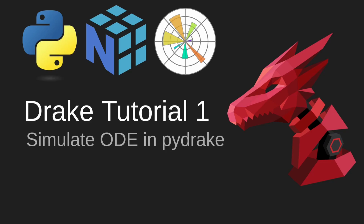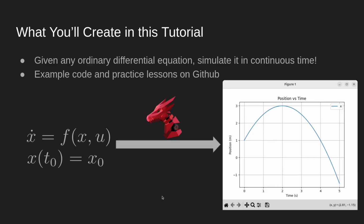Let's get started. Given some ODE, we can always represent it in some state space format, x dot equals f of x and u, where x represents our state vector and u represents our system input. By writing just a few lines of Python code, you can use the simulator inside of Drake to simulate your system given some input signal u and some initial condition x naught. You will also see how to use matplotlib to create an interactive graph like you see on the right, but in future videos you'll also learn how to create a 3D animation of your system using Meshcat.